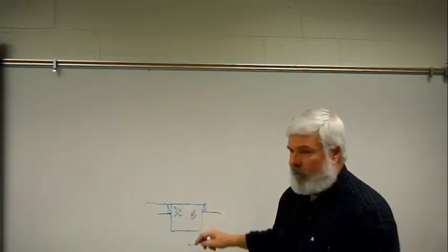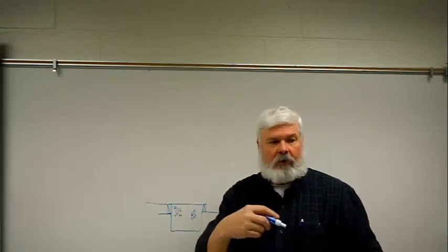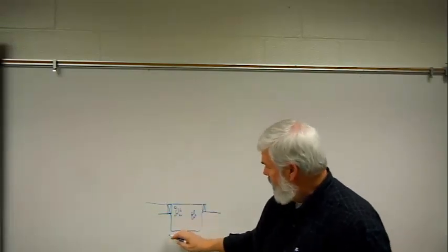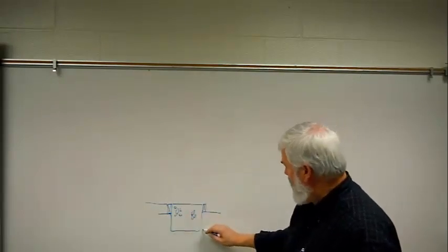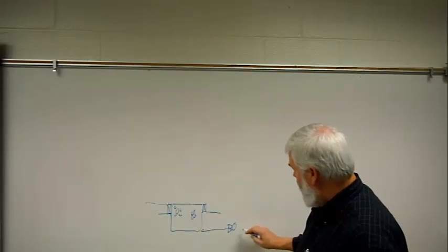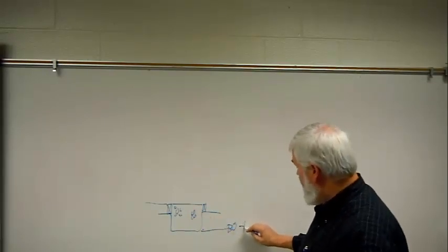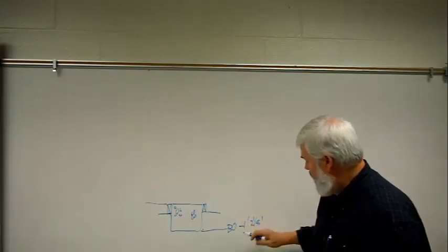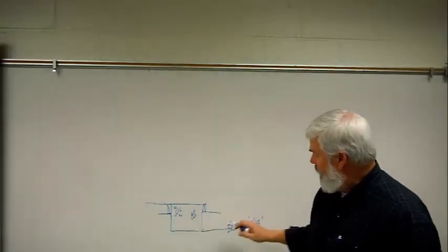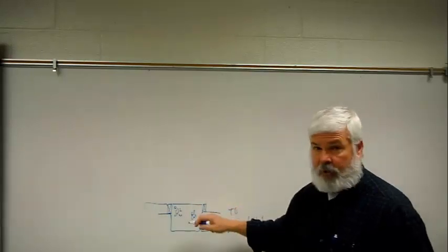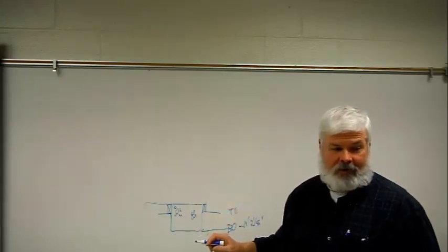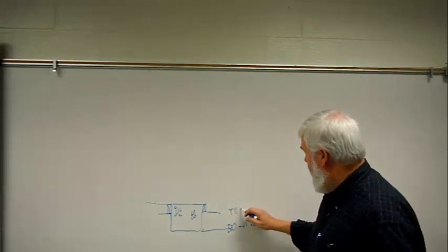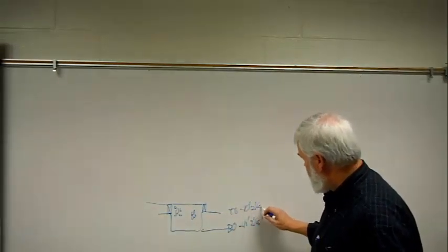and so the footing that I'm giving you instructions to set up in your Revit template is 12 inches deep. That's the depth of the footing, and it starts here at the bottom of the footing. Your BO level is, and somebody check this to make sure I'm right, minus 11 feet 2 1/8 inches. Is that right? Yep. Okay. The top of the footing is going to be where, the TO, if this is a 12-inch deep footing? 10 2 1/8. Okay, minus 10 foot 2 1/8 inches.